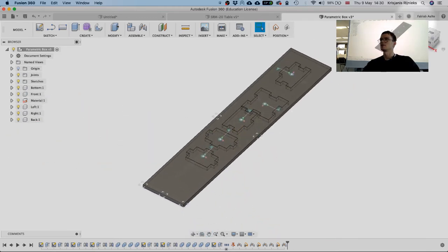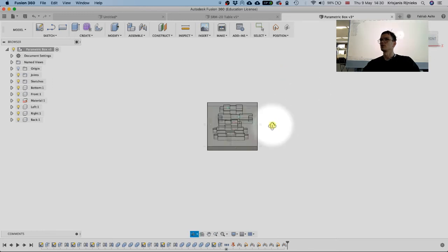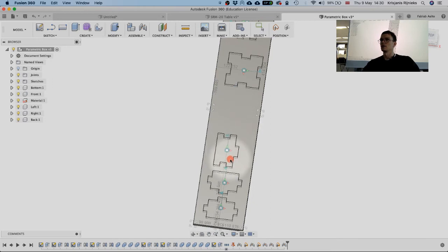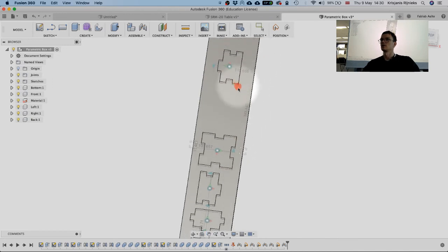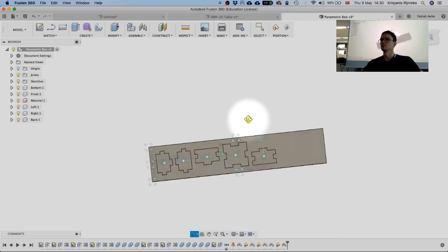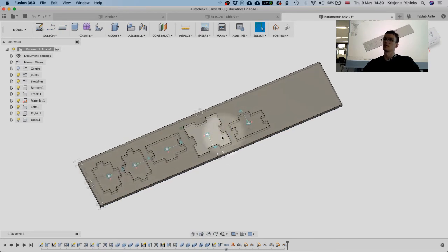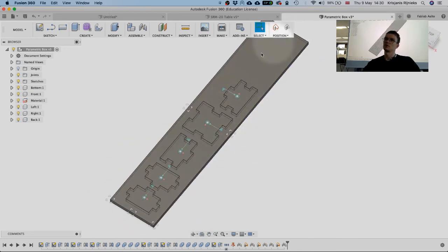And let's check. If we are looking at it from the front, then we want to save the material as much as possible also. So we are going to lay it out in a more economic fashion. Not the most economic one, but still. Like so. Yeah, so now we have it. So it's laid out. So this is how it's going to look on the CNC machine.